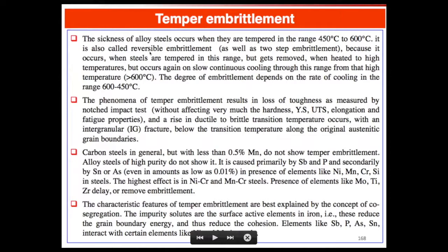And this was called reversible because, well, temper-martensite embrittlement was considered irreversible because once you dissolve the grain boundary cementite off at a higher temperature, cooling back down, you won't grow a new grain boundary cementite layer.